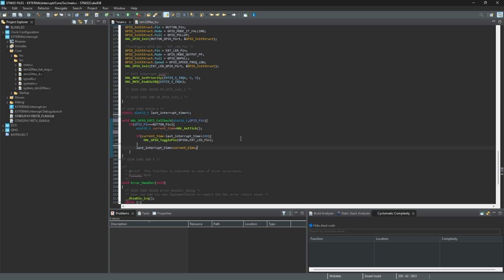So if you are asking why are we using the debounce? So the software debounce that we have created is because mechanical buttons are dirty signal. And when you press them, the metal plates vibrate. Therefore, it's going to create tiny zeros and ones, or the on and off signal, in a few milliseconds. So without debouncing, the LED would toggle like 5 to 10 times in a microsecond, appearing either off or flickery.